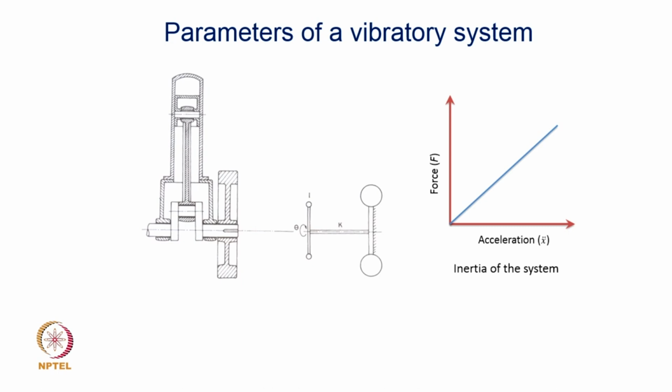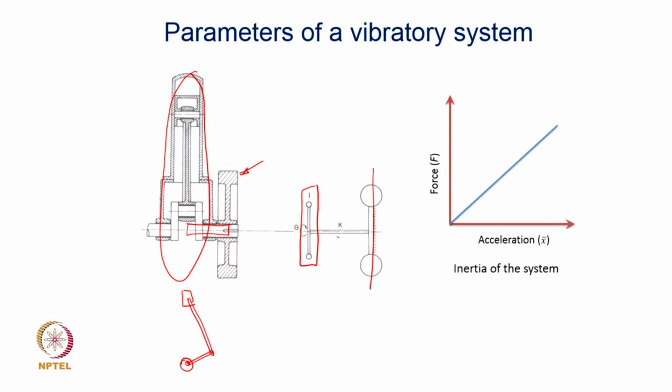The example I am taking is of a simple IC engine where a flywheel can be treated like a huge mass which can be treated as fixed, and this shaft can be treated as your stiffness element, and this entire mechanism, crank, connecting rod and piston itself is your inertia in a torsional vibration setting. This entire mechanism itself is like an inertia at the tip of this crankshaft, right. So, one can find out what the stiffness is, but when you look at the inertia, this is a mechanism which has a moving piston and an oscillating and rotating connecting rod and a crank here.